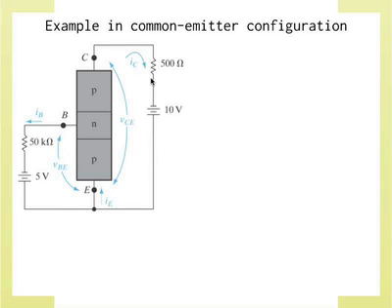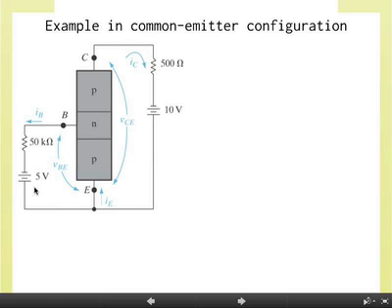The base should be, right? The base current? Yes, it's still the base current in this situation. It is the base current; it was the emitter before. Because the same principle applies, right? This idea that we talked about of restricting and increasing the base current affecting the collector current still applies. The base current is still our control. Or you can think about this voltage being our control. You can put a small signal voltage on here, which of course will give you a small signal current. Remember, it's forward biased.